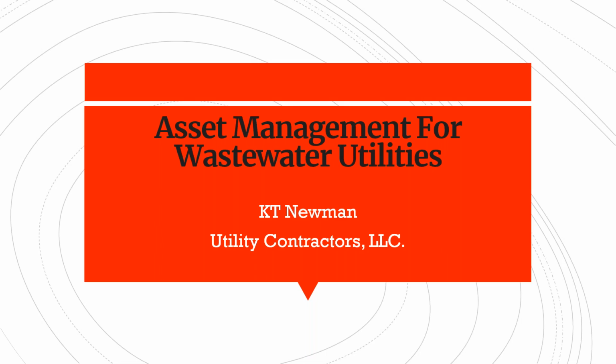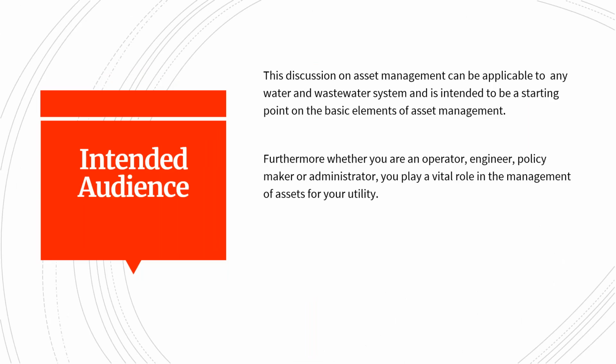Asset management provides utility managers and decision makers with critical information on capital assets and timing of investments. Some key steps for asset management are making an inventory of critical assets, evaluating their condition and performance, and developing plans to maintain, repair, and replace assets and to fund these activities.